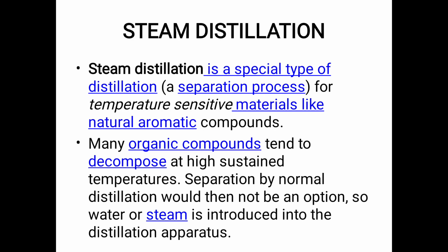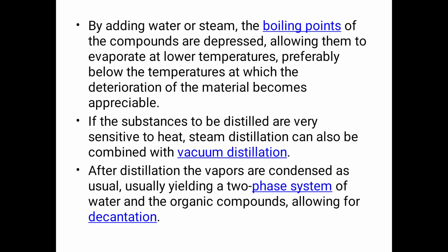It is mainly used for heat sensitive material, that is temperature sensitive material like natural aromatic components, etc. Many organic components tend to decompose at high sustained temperature. Separation by normal distillation would then not be an option, so water or steam is introduced into the distillation apparatus. By adding water or steam, the boiling points of the components are depressed, allowing them to evaporate at lower temperature, preferably below the temperature at which deterioration of the material becomes appreciable.